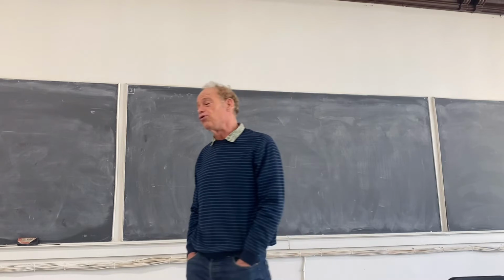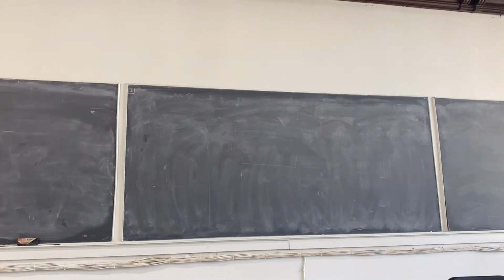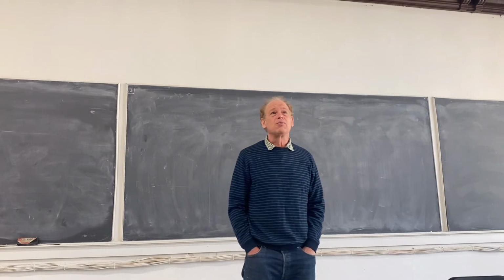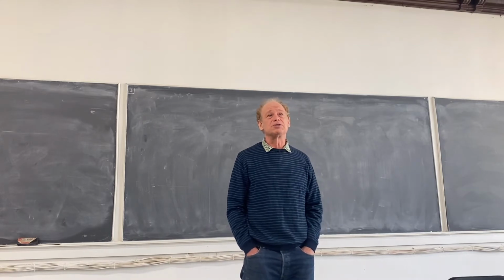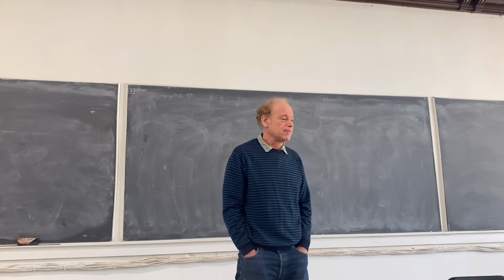So to get from moles per unit volume time to energy per unit time, you have to multiply by energy per mole, minus delta H, times volume, which is the volume of the reactor. So units are important. You can't have an equation where different terms of the equation have different units. Doesn't make sense.